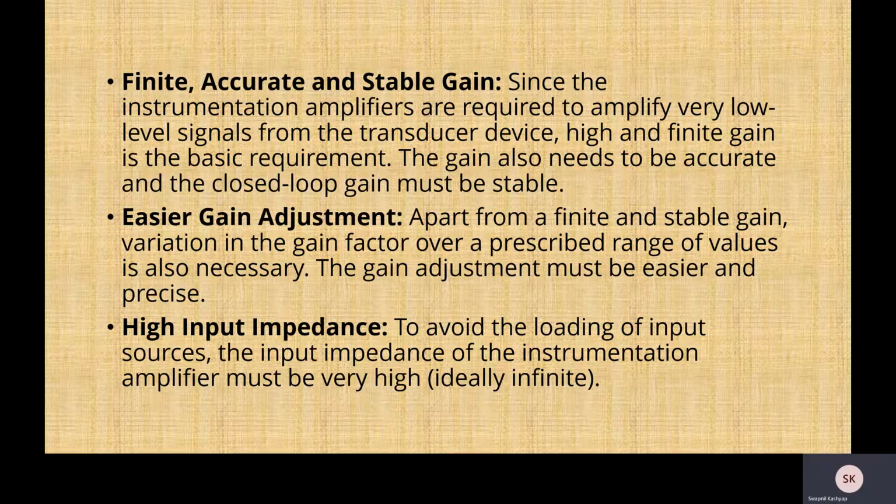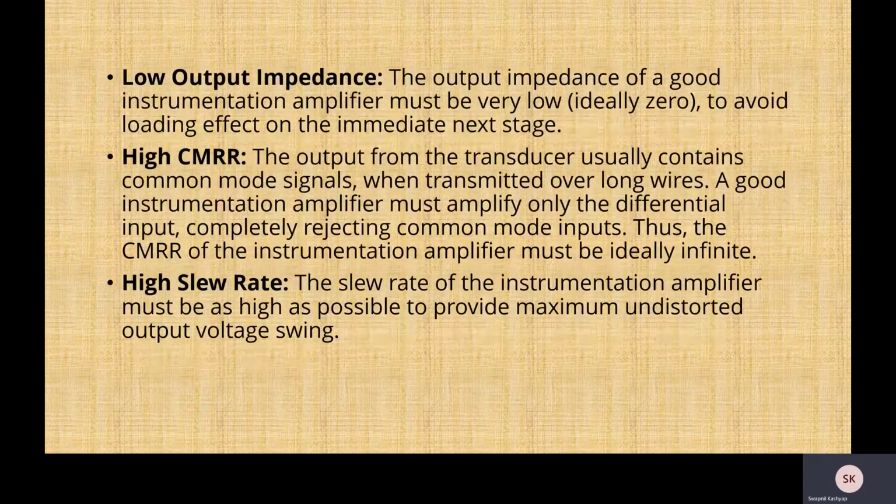High input impedance. To avoid the loading of input sources, the input impedance of the instrumentation amplifier must be very high, ideally infinite. Low output impedance. The output impedance of a good instrumentation amplifier must be very low, ideally zero, to avoid loading effect on the immediate next stage.